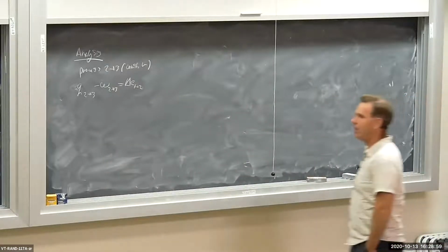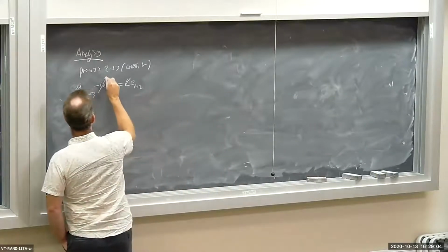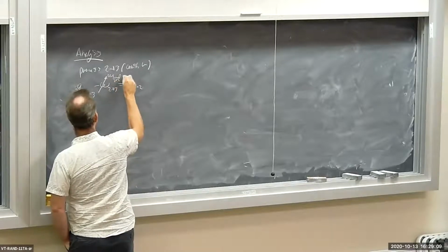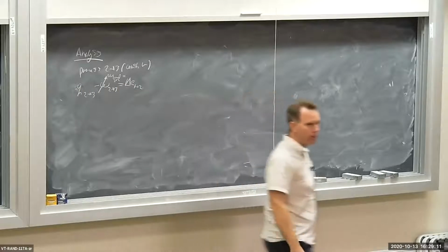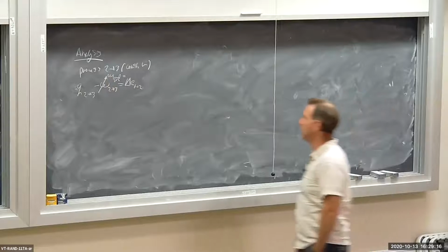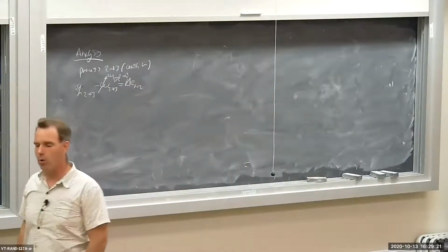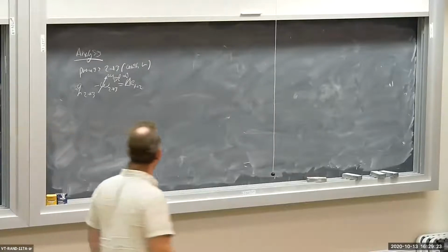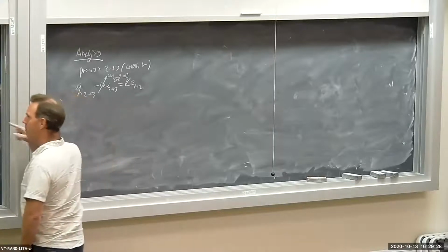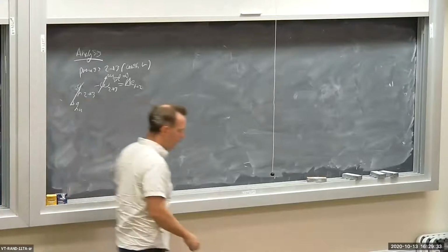Now, the cycle analysis assumption says that the work W is boundary work. So this is W bound from 2 to 3. If it's an isochoric process, 2 to 3, what's the boundary work? 0. It's isochoric, constant volume, so the integral of PdV is 0. The heat transfer, Q from 2 to 3, is the heat input. So this is Q_in, which is what I want.